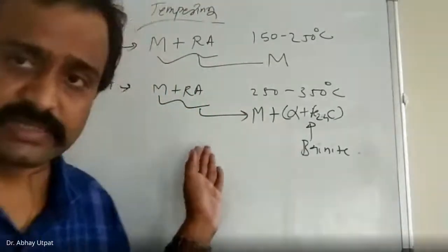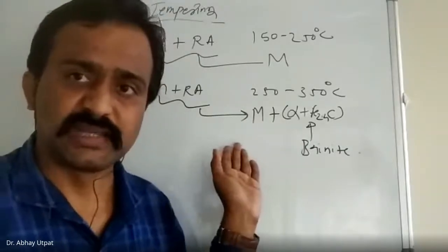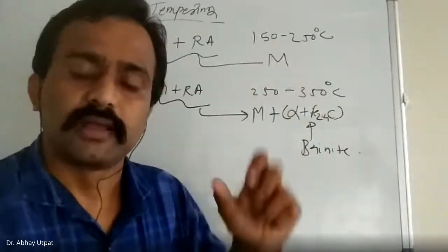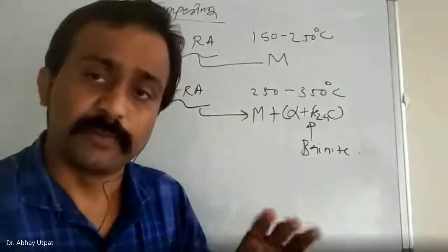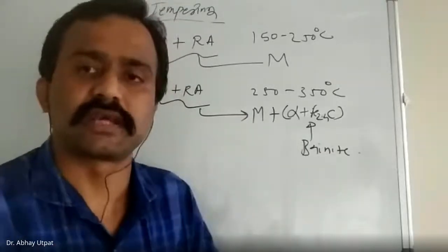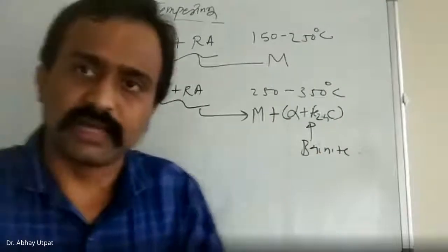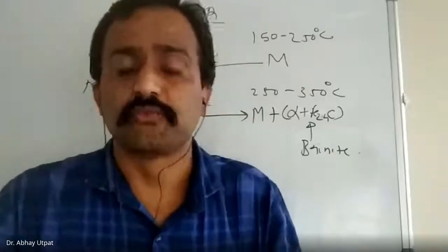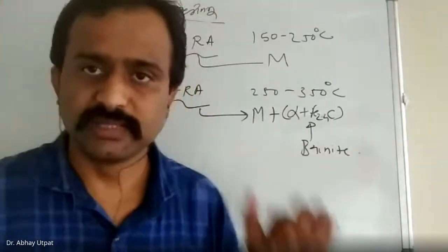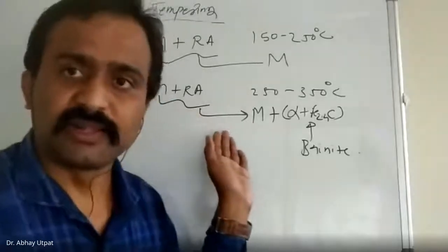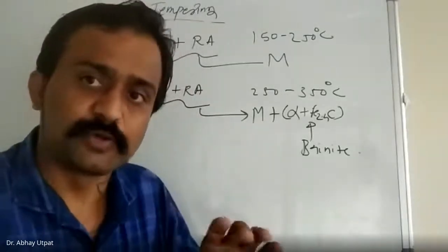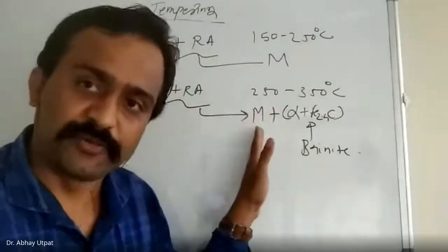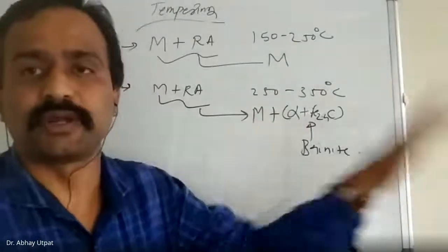Generally, medium temperature tempering is given to springs, links, and similar components that are subjected to shock. More hardness, 50 RC, but less toughness is not desirable. So with a little compromise in the hardness and improvement in the toughness, the overall increase in properties will increase the life of the component. Hence, medium temperature tempering will give sufficient hardness and good toughness, so that the life of the component increases.